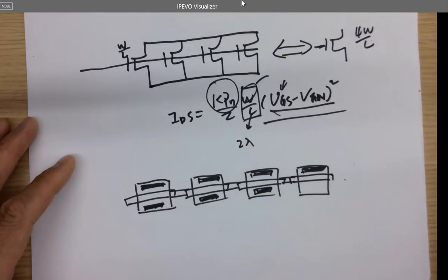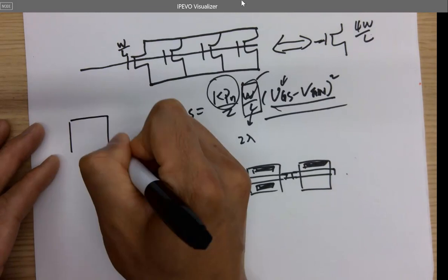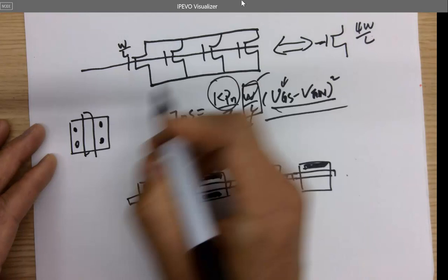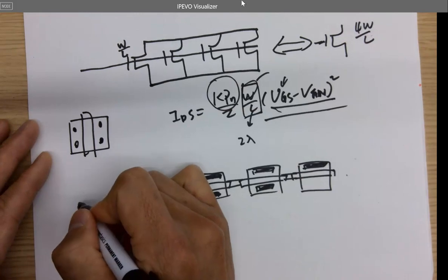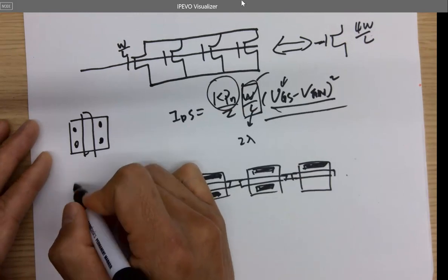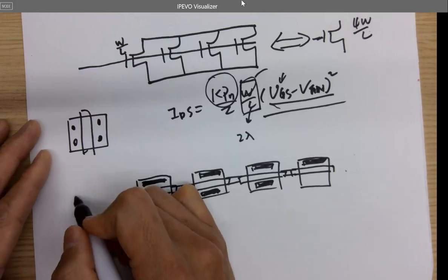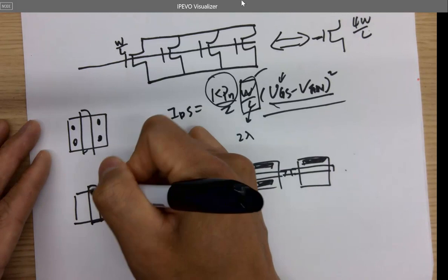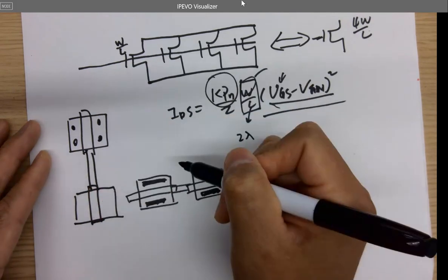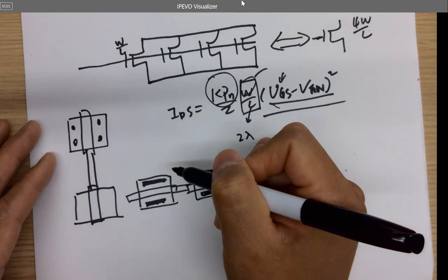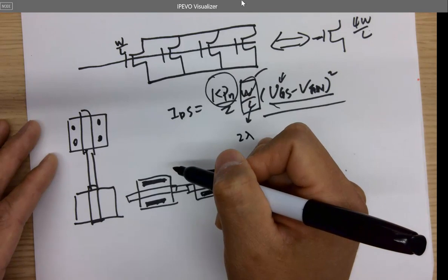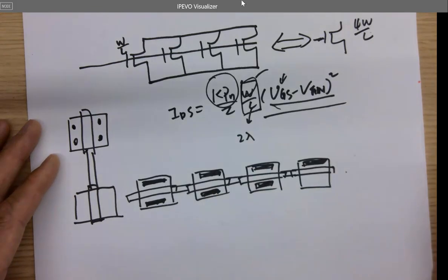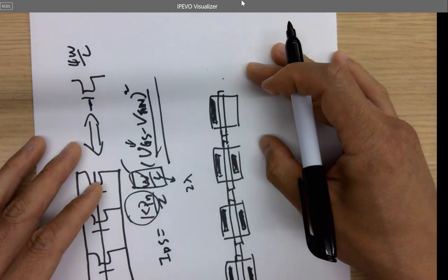Another reason for that is for the inverter. You're talking about the inverter we did, right? Because we have a CMOS, not NMOS, and you have PMOS on the top and NMOS at the bottom. So you have the poly being put together like that, so you can directly do this connection for the gates. Yeah. You just do it like that, right?